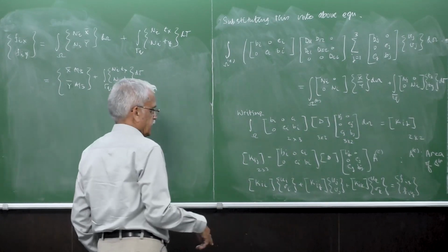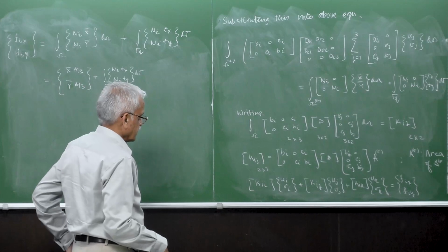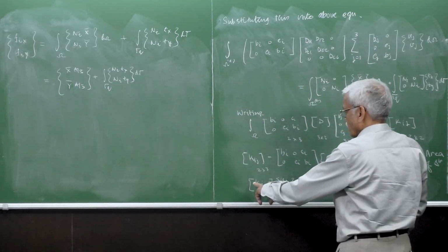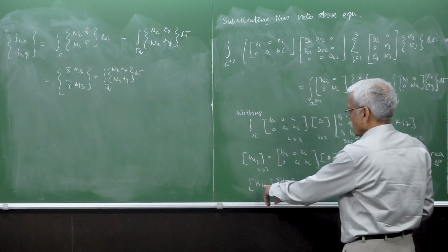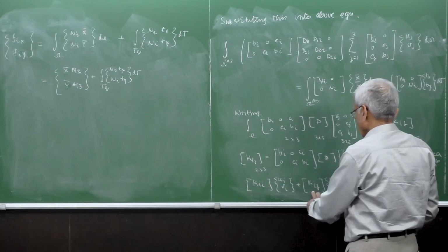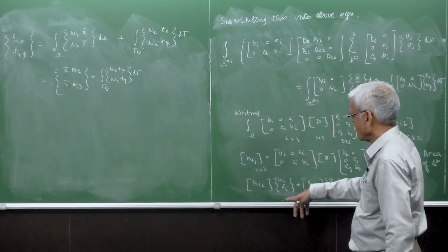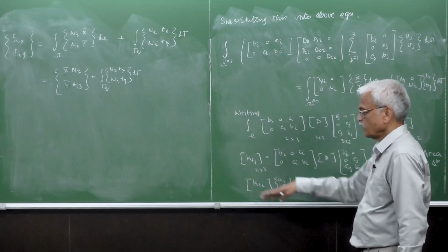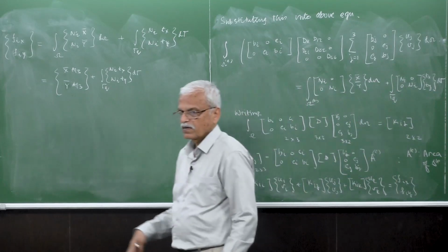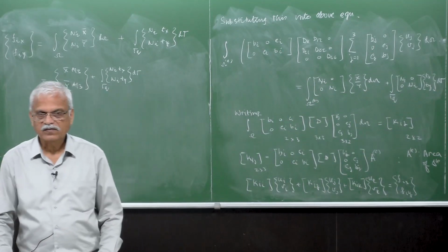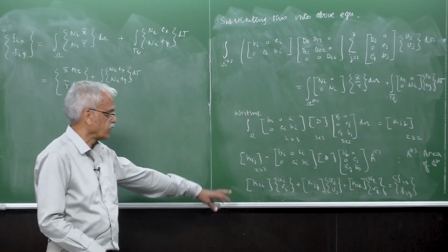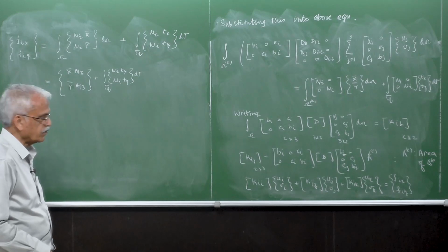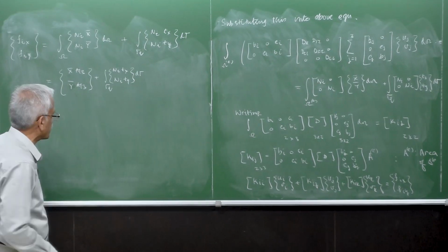So the equations here will come out as the 2 equations, now put in the matrix form. So it's Ki, each of these submatrices are 2 by 2 matrices, and Ui, Vi, Uj, Vj, Uk, Vk. So this is a set of 2 equations in the x direction and y direction corresponding to the weighting function being the trial function of ith node.